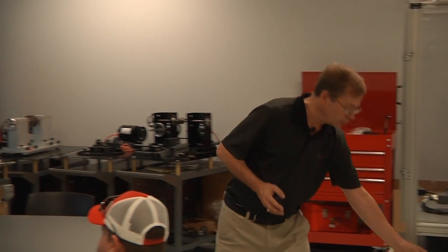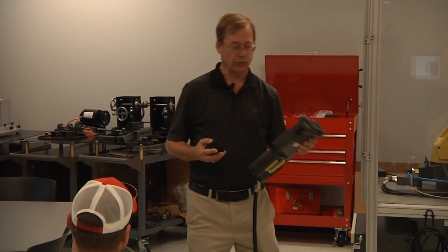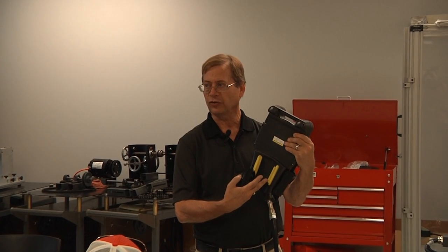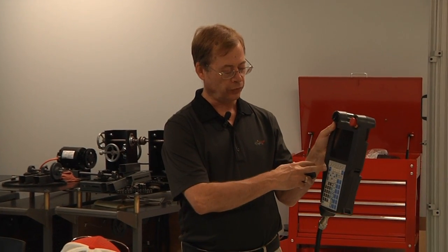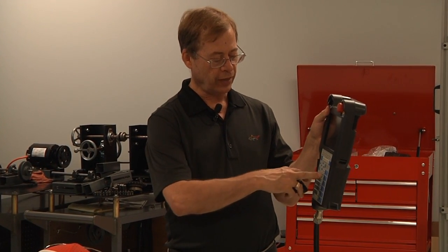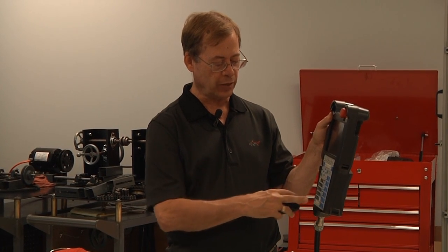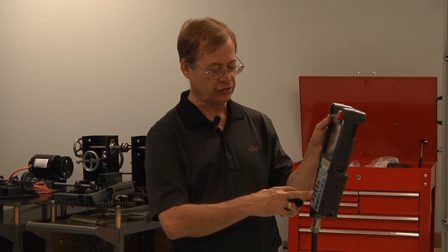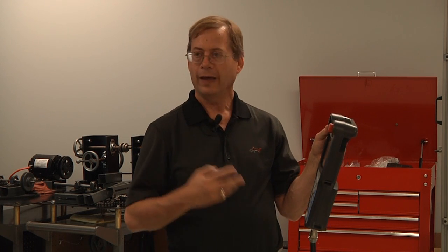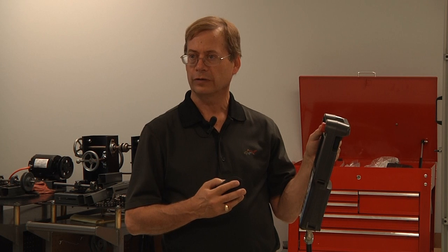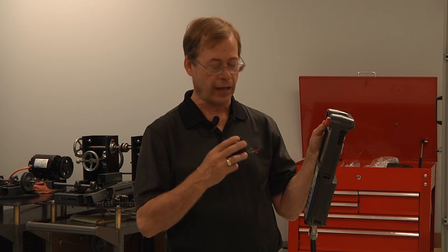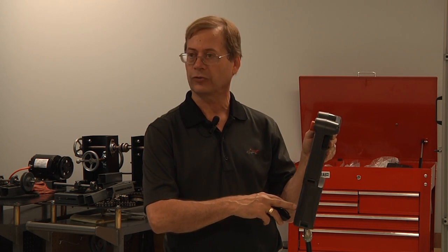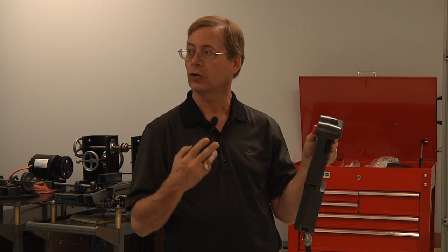So to use the teach pendant, the robot has to be in teach. You have to have the live man switch in the center position. You have to hold the shift key down. And then there are 6 pairs of blue buttons labeled J1 minus, J1 plus, J2, J3, J4, J5, J6. This is how you jog the axes. If I want to jog axis 3 in a positive direction, I would press the plus J3 button and it would jog until I let go of the button.